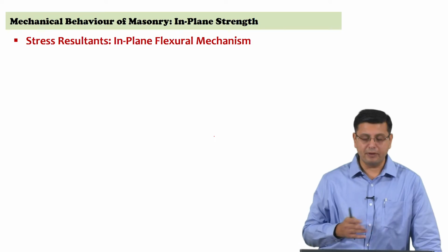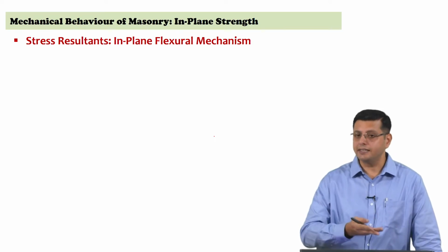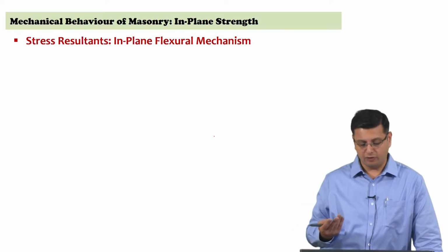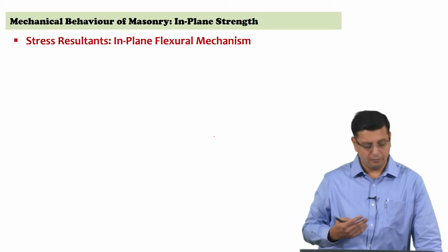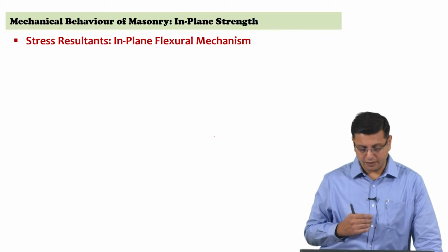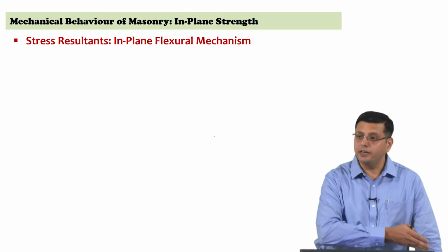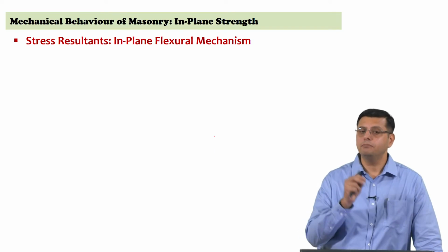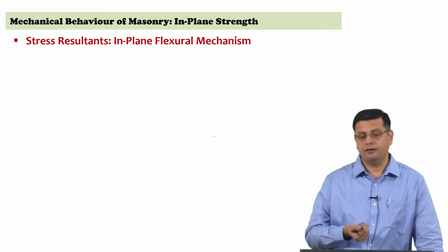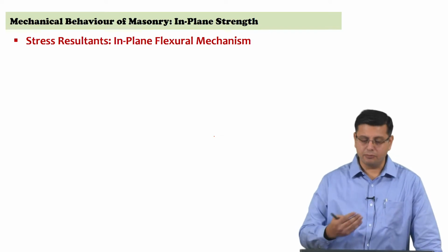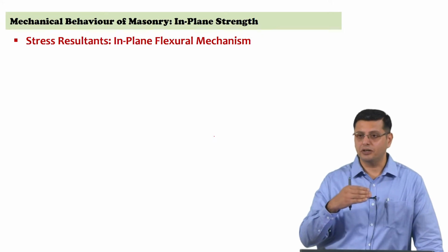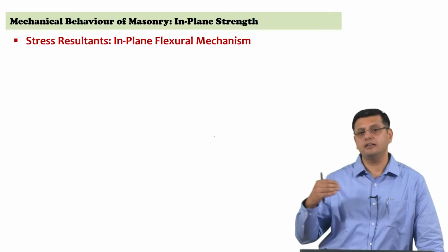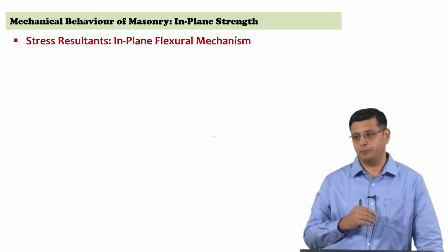We will examine a wall which is free to rotate, cantilevered in the lateral deformed shape, rather than a shear deformation profile because of the top rotational restraint. And then of course, we have already examined the role played by the material strengths. You can have the relative strengths between the bed joint shear strength, the compression strength of masonry, and the tensile strength of masonry.